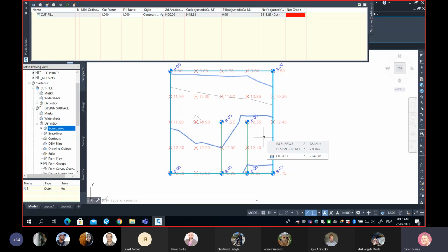If you remember, the contour line done using Civil 3D is better simply because it interpolates along the diagonals in addition to the four sides of the square. So it gives you a kind of refined version of your contour line. It breaks at the diagonal. And I think we discussed also that the diagonal is not easy to tell, so the software has to do a lot of calculation to find the diagonal.